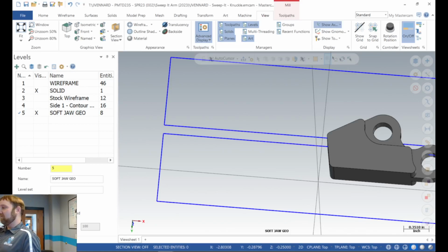And more efficiently, because when they saw that we had built that fixture here in house and brought it along with us, it was a way to take a 3-axis capable machine, we didn't have a multi-axis, and create a finished part without having to open the door. Every time, once the part got through all 5 stations, another part was following up and would cycle out.